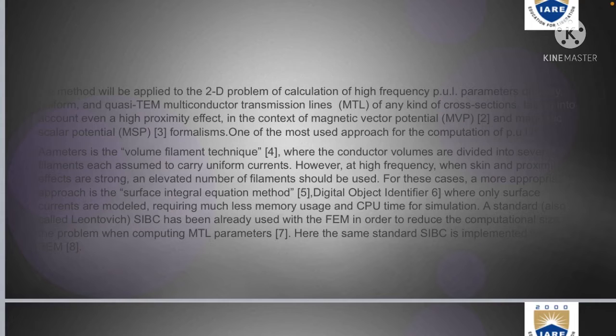A standard SIBC, also called Leontovich SIBC, has already been used with the FEM in order to reduce the computational size of the problem when computing MTL parameters. Here, the same standard SIBC is implemented with the BEM.